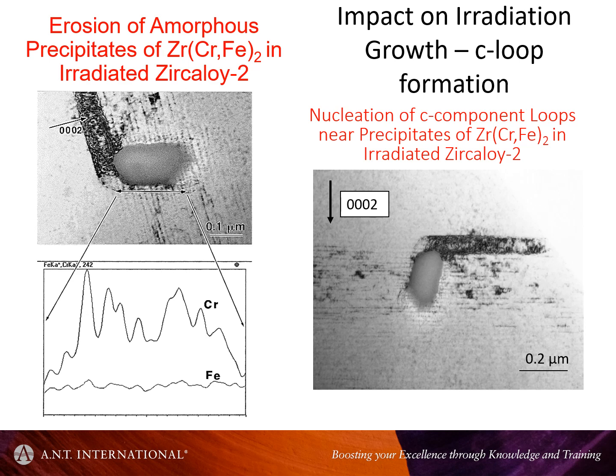But what they failed at the time to understand was that they were looking at the ion damage from the ion milling that they used to create the samples. The ion milling was performed at room temperature, and the precipitates which were sticking out of the surface became amorphous, where the ion beam, which was a slanted, glancing angle ion beam, intersected the precipitate. That formed the basis of a lot of theory going on about ballistic mixing and stuff like that, which I never believed. But you know, anything can happen.